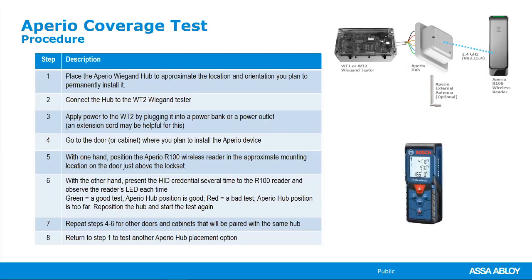One other thing I suggest that's not needed, but a digital tape measure. This will save you from having to pull a tape measure all through your hallways. At this point, once you find the max distance, you just point and shoot the wall and it'll give you that distance and you can write it down so that as you're going through doing your survey and figuring out what the scope of this project's going to look like, you'll be able to do it much easier.